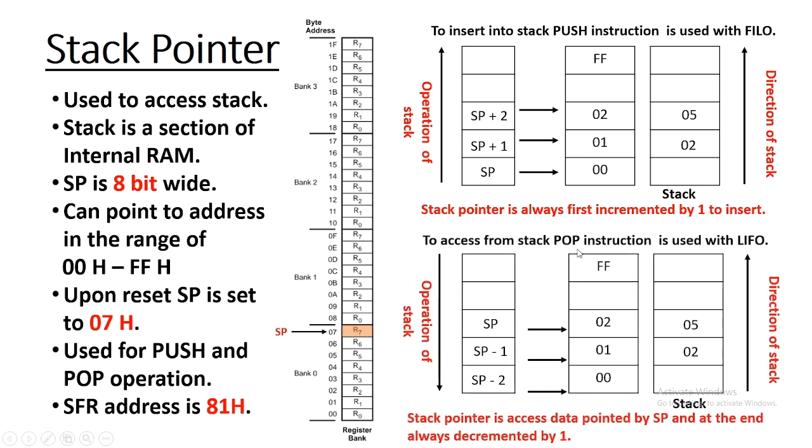To retrieve data from the stack, we use a pop instruction. It is used with LIFO, last in first out. So the stack pointer accesses data pointed to by SP, and at the end it is decremented by 1. Suppose the stack pointer is pointing to the top of the stack. If you want to retrieve data from the stack, the pop instruction is used, and the data from the location which is pointed to by the SP is fetched and then SP is decremented.